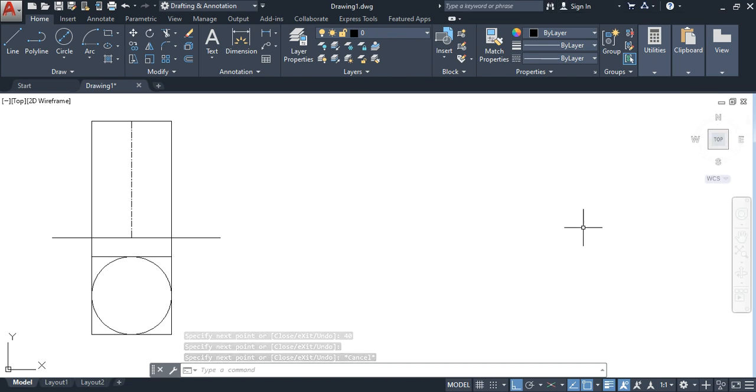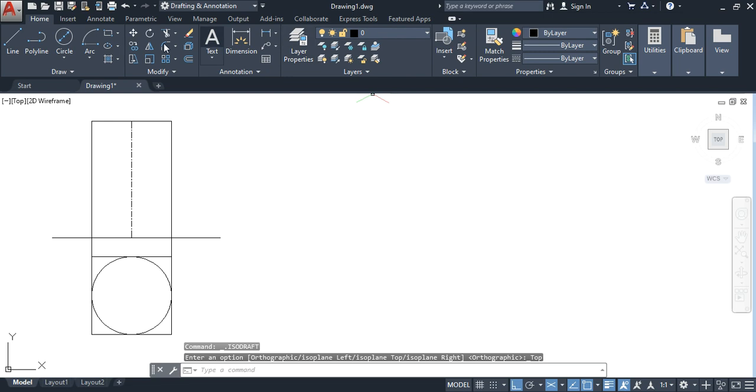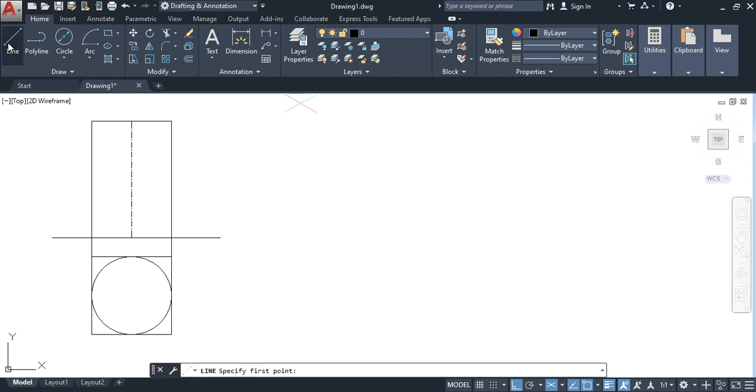Without inscribing also we can draw, means we'll develop a circle in the isometric view. For that we require these center points. So anyway, we draw the isometric view of, first of all, this square, and after that we will draw the circle in isometric view.